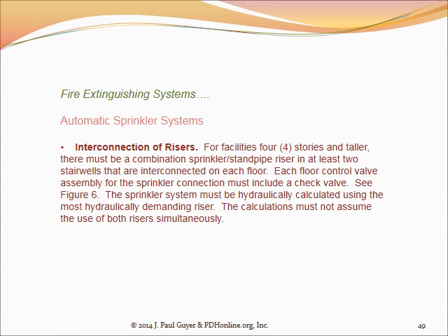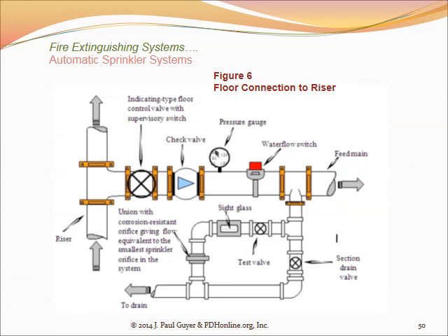Now, I was talking earlier about the wet or dry standpipe. This is the pipe, again, using the illustration of a multi-story building, 5, 10 stories high or whatever, and the fire protection water enters the building through a connection on the outside wall and rises vertically in a pipe, a standpipe, vertically up to the roof.